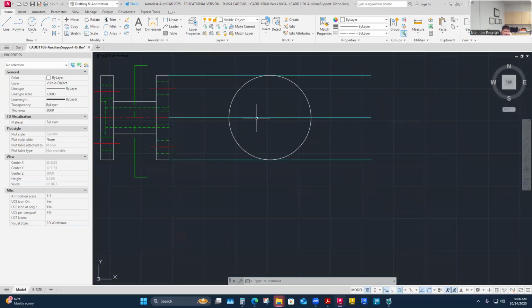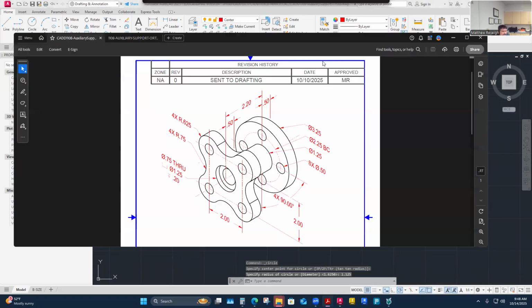And it's going to have its hole pattern, which I can choose to do, or I can draw in. It's definitely going to need a center line hole pattern. That same bolt circle pattern is what I kind of need. And it had a bolt circle pattern that was, I think, 2 1/4. Does that sound right? 2 1/4, 1 1/8, maybe. I'll double check that. I got 1.125 as my guess, but let me just make sure that's right. Yeah, this is a 2 1/4 bolt circle. So I did a radius circle that's 1 1/8. That's half of that.